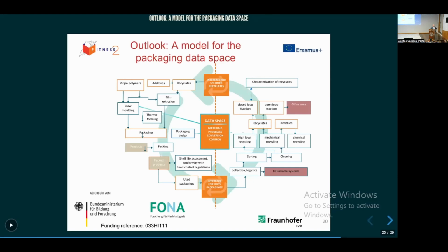Yes. There's two aspects of this. And with the containers, we are talking about maximum of 60 nanometers, for instance. If you relate this to the whole amount of material that's being involved, let's say 300 micrometers of plastic, then the relation between the coating and the polymer is so small, coating versus polymer, that it does not harm the recycling process.